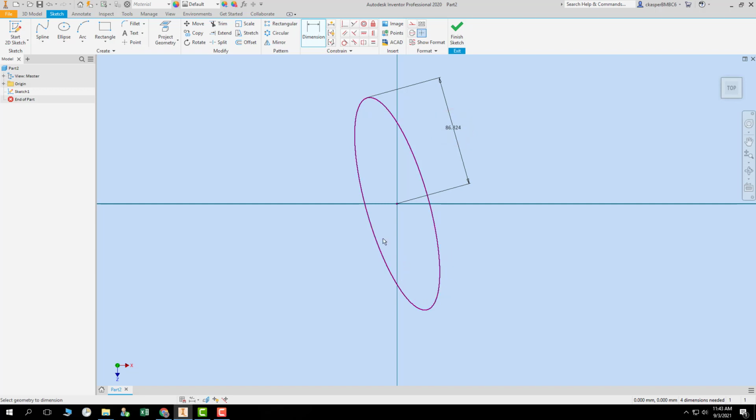Now I believe if you go to dimension and click on it, you can set your top dimension there. Oh, that's top dimension again. Just click on dimension, click on the top, and here's your width. So we can manually type that in, make it 25 millimeters, and the upper part of this is basically radiuses.